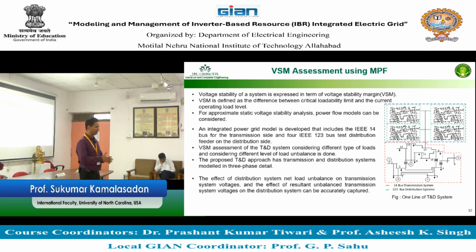So the value quality, we talk about what? The value of the voltage that you get could be good, the value of the frequency that you get good. We care less about the angle, but angle is also important. That's parameter, and we look into time. We talk about the quality with respect to larger time, smaller time, and very small time. So very small time quality, we call it transient quality, and that is assessed by transient stability tools, transient stability analysis. Such tools are called TSA.